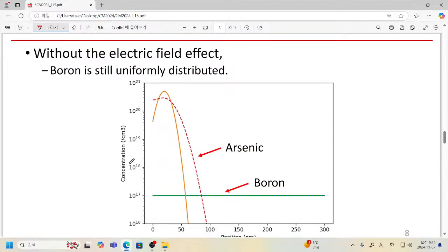Now you can see that if we apply certain heat, the peak point doesn't change much, because it always diffuses over non-peak points. So usually the peak does not move quite fast, and after that, here you can see the extension of the metallurgical junction. It is because previously highly concentrated donors are now diffused and their concentration is a little bit blurred.